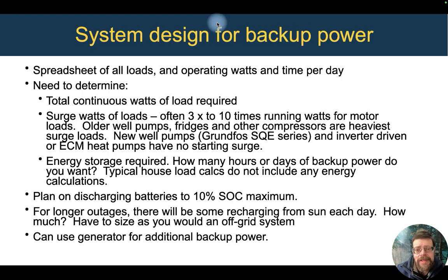So that's why we use 80 to 90% of the storage rather than 100%. When we're doing a system design, we want to start with a spreadsheet of all the different loads, how many watts each load is, and how many hours per day it's going to be operating. That'll let us calculate the watt hours each day that it's going to use. There are a lot of general estimates that people try to use instead of doing the full spreadsheet, but the proper way is the full spreadsheet, with all the loads that you want to back up and an estimate of how many hours per day each one's going to operate.